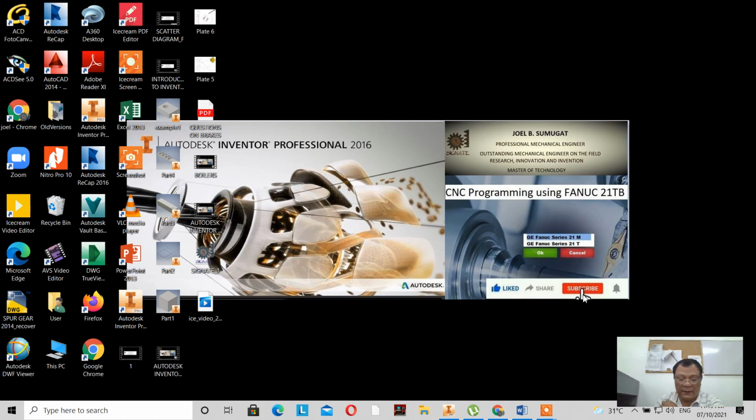Now, I'm talking about the mirror tool. Well, all CAD software uses this tool. Now, it is a very useful tool in the design when you're working with a symmetric profile. It means that instead of drawing the whole profile, you can concentrate only on half of the profile and then use the mirror tool to mirror it.